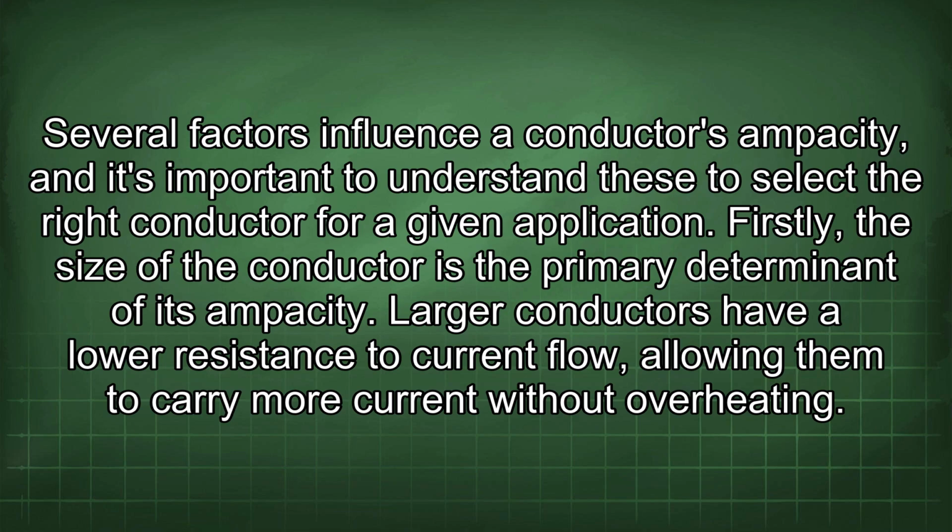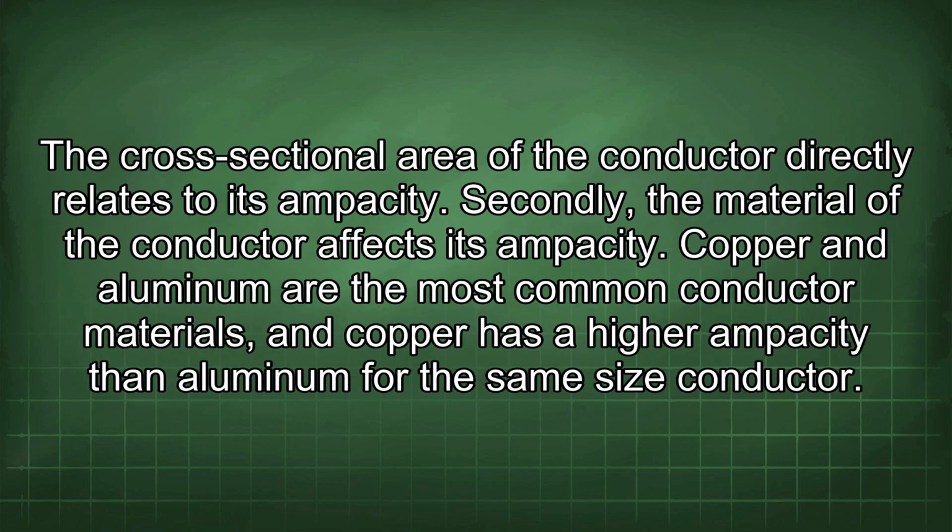application. Firstly, the size of the conductor is the primary determinant of its ampacity. Larger conductors have a lower resistance to current flow, allowing them to carry more current without overheating. The cross-sectional area of the conductor directly relates to its ampacity.